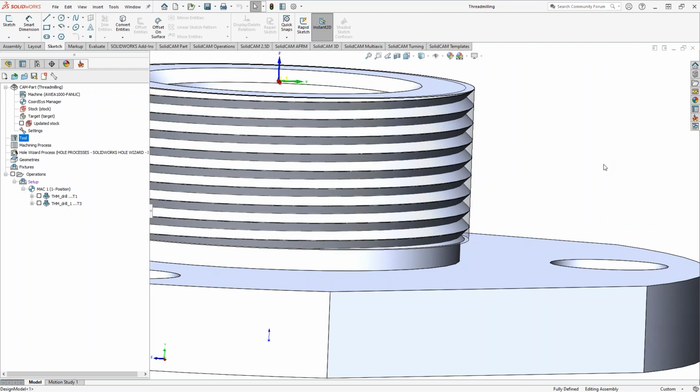It might look like it's some sort of a gouge when really it's not. Especially in turning, I would definitely say you don't want to see that, because remember, in turning, when you generate your target profile, it does that cross section, it does that revolve. You're going to get some weird geometry over here that is trying to approximate what that surface would look like. If you're doing a turning thread, this is not thread milling, but this is just kind of threading and turning, have it as just that cylindrical representation.